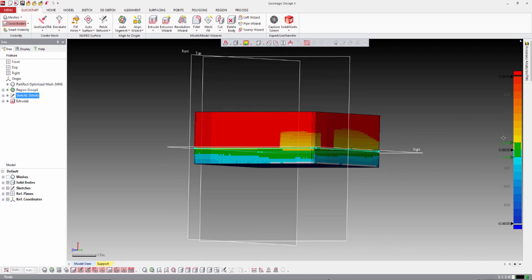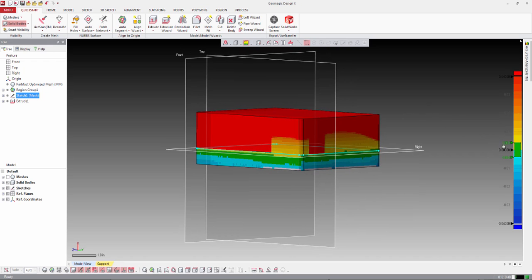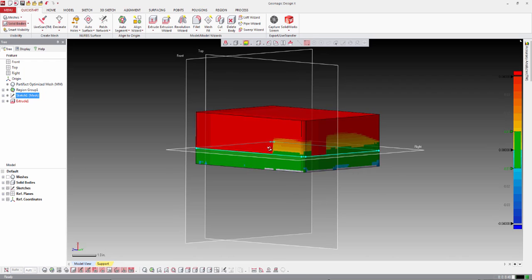And what we're presented with is a color map. So based on some nominal values of deviation, say plus or minus 4 thousandths of an inch right now, we can make this looser, maybe a little more realistic, plus or minus 10 thousandths of an inch. That this wall doesn't quite match up to the scan data.